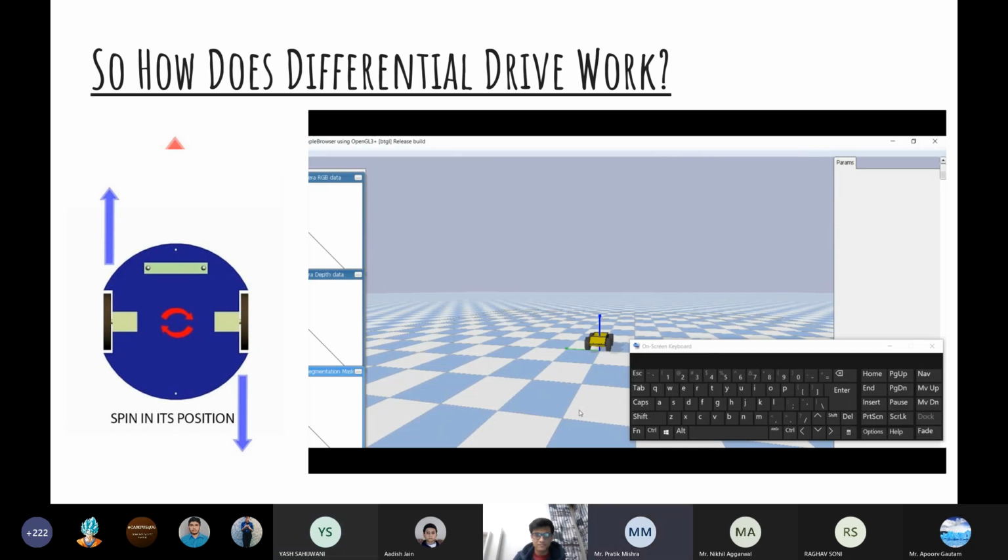So in this bot also we have to use a differential to change the velocities, no? Yes, in this bot that you will control inside PyBullet, you don't have rotation in your wheels. So you can't rotate your wheels like you do in a real car. The only option that enables you to turn is using this differential drive. You can rotate your wheel, but you can't change their direction or their axis. In real-world cars, most common cars, you change the axis of your wheels. You rotate them left or right, and your car turns that way. That is not differential drive.